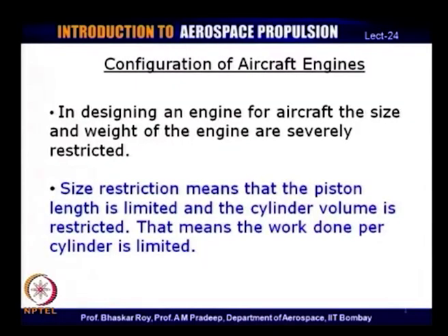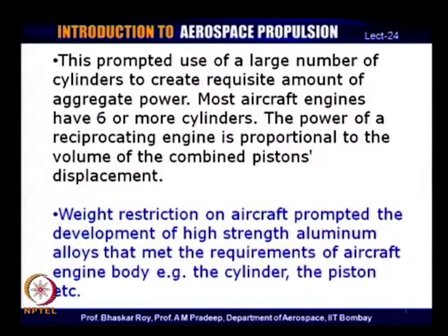As a result of these restrictions, the work done per cylinder in a piston engine that goes on an aircraft tends to get somewhat limited, and this limitation is what aircraft engine designers have to live with. Now, to make an aircraft fly, you need a certain aggregate amount of power, and to get this aggregate power, you need to put together a number of cylinders.